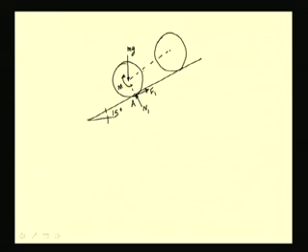At this contact point C, we have the normal reaction, let us call it N2, and since this roller is slipping at this point C in the counterclockwise direction, the direction of the frictional force is opposing the same, and the same is marked here.